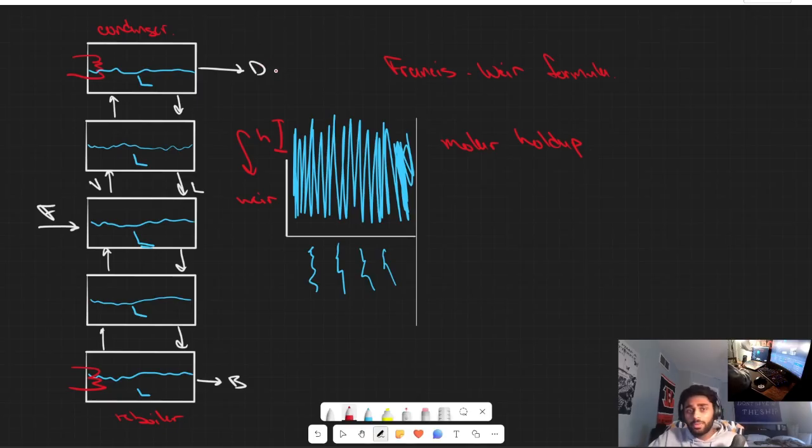So you would expect that with a higher reflux ratio, we'd have a larger liquid molar flux going through our distillation column, and thus the thickness of this molar holdup would be greater. So today we will be doing a simulation of that molar holdup, as well as determining the molar compositions of our more volatile component as we go through our distillation column. And finally, we will put all that data together into a McCabe-Thiele diagram to visualize how we would set up this distillation column given certain requirements.